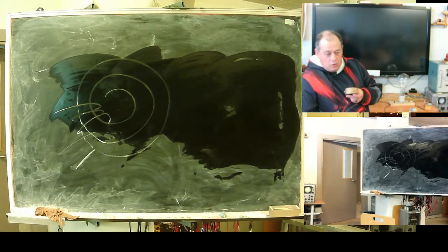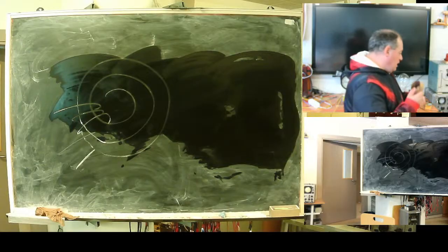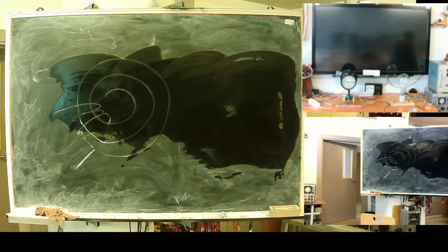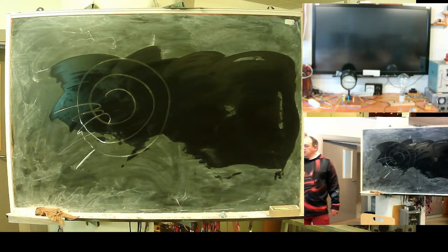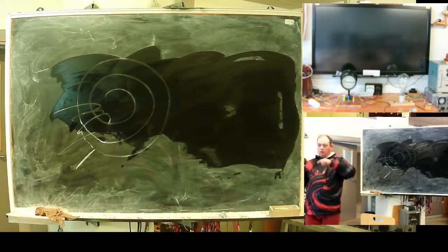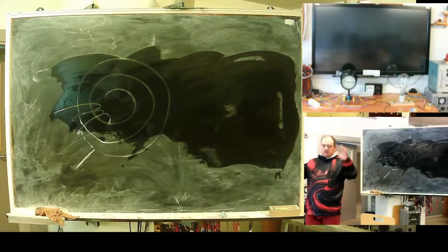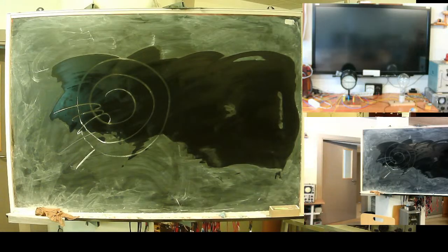What's done? Immerse in a hot compound, vacuum immerse, and then hot drying. And before, what is done by a good manufacturer? They perform thermocycling. After being wound and welded at one point, this core goes through thermocycling when it's heated and slowly cooled. This makes the steel structure uniform.